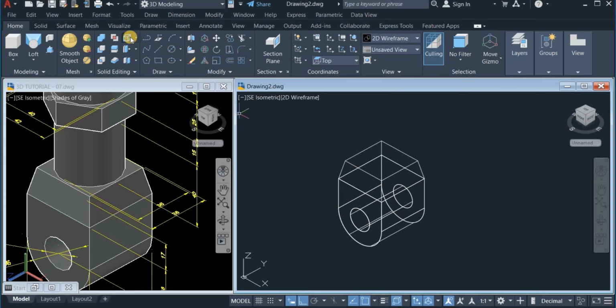So come over here again, click on this, and also click on this very one. Okay, so I now have broken lines again. So use the join command again to join these lines. So come to the modify panel, click and choose join, and join these 4 lines. Okay, so I now have a square again.